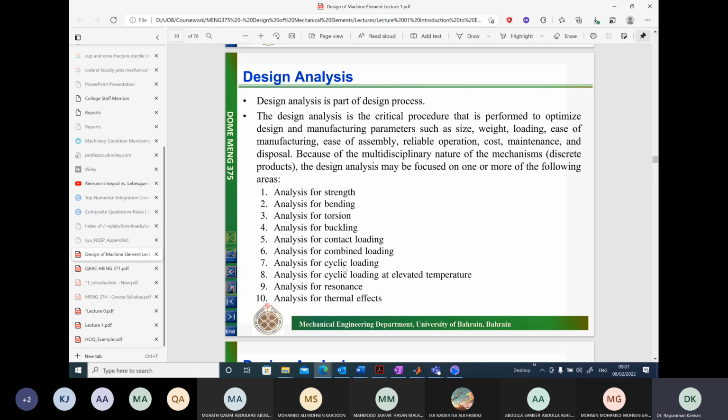So these are some basic design rules you might have in your mind when you are designing some product. It is also better to avoid any cyclic load if possible. Otherwise, you will have cyclic load. And in case of cyclic load also, it is better to have tensile and compressive loads in comparison to bending loads. Again, when you have cyclic bending loads, the product will break faster than with cyclic tensile and compressive loads.